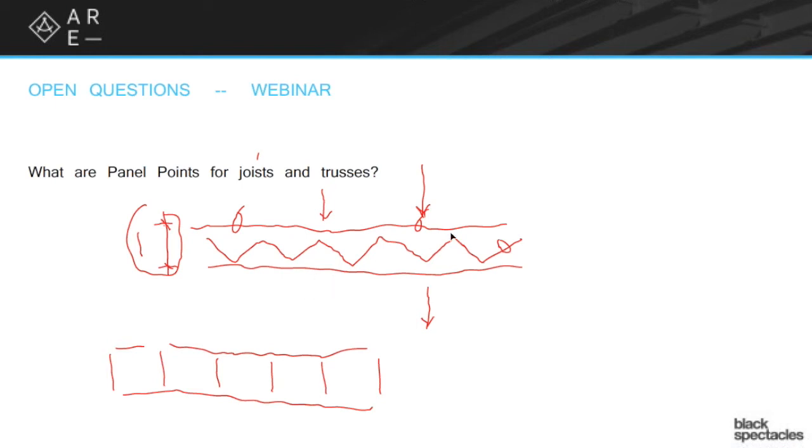Pretty much all the other trusses, you'll still follow all of the same basics, whether the top chord and the bottom chord are parallel. Doesn't really matter as long as there are triangles, as long as the overall system is made out of pin joints, and as long as the loading is done on the panel points. That's all still considered a truss, no matter what the shape is.